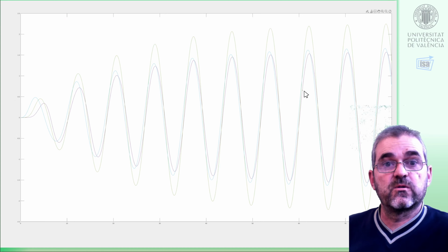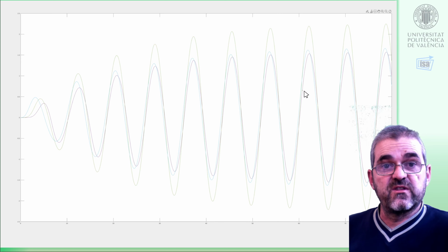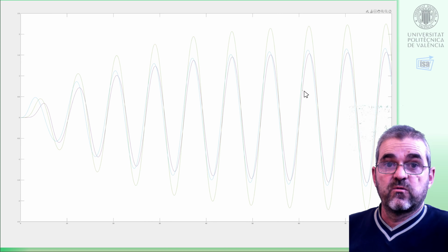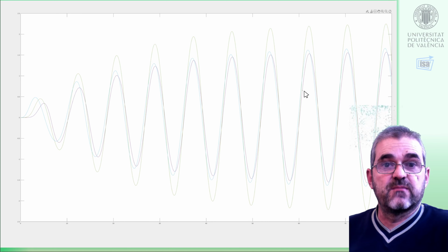So we'll summarize and conclude. In this video, we are just discussing how to encode the linear system of equations. It's easy, just copying A, B, C, D. And once we define initial conditions and input, we can solve it with a generic solver, such as ode45, or we can simulate the time response with a specialized solver for linear systems, such as lsim. We did both ways here to compare, but of course, in a real setup, I would use ode45 if my system is nonlinear, and lsim if my system is linear.